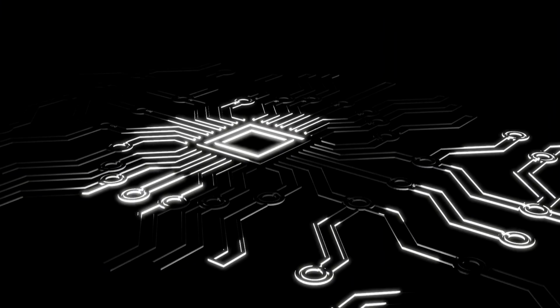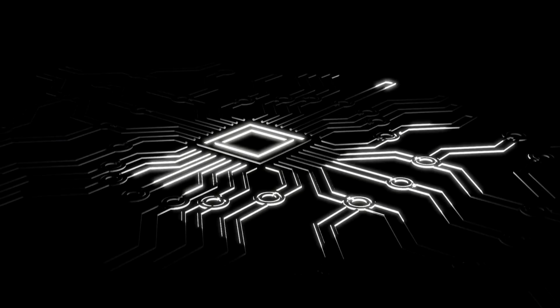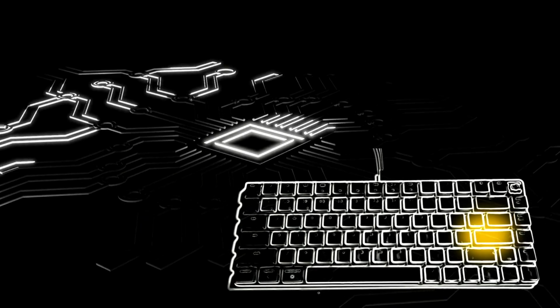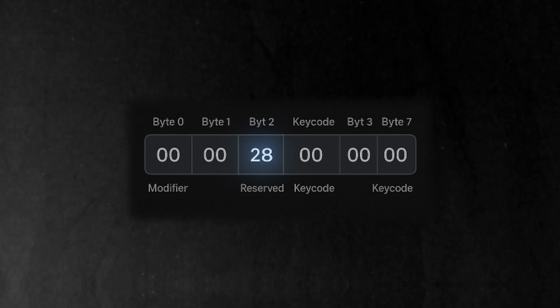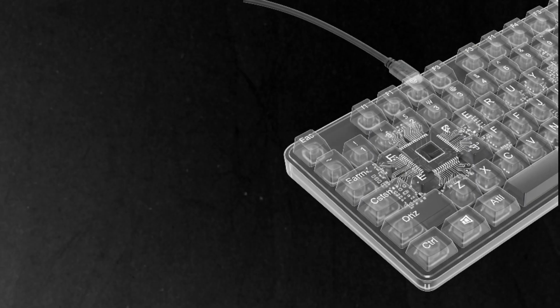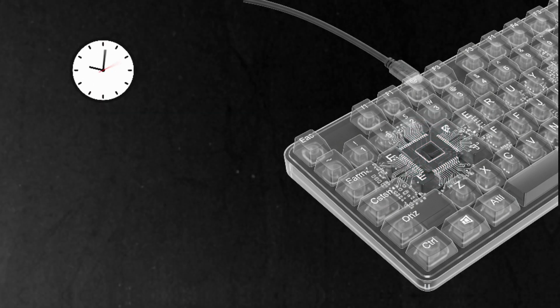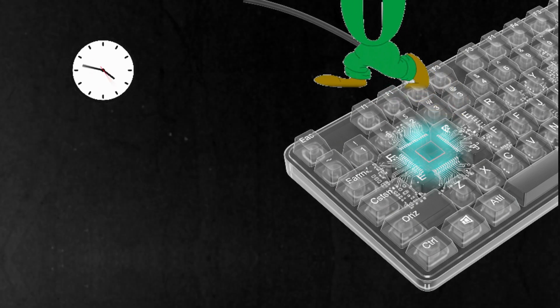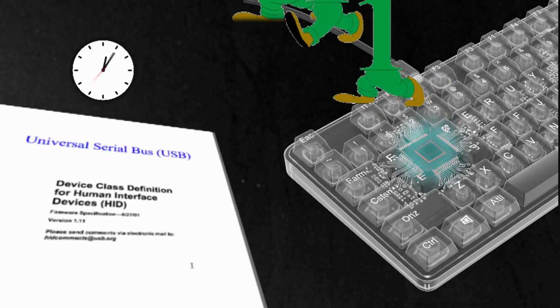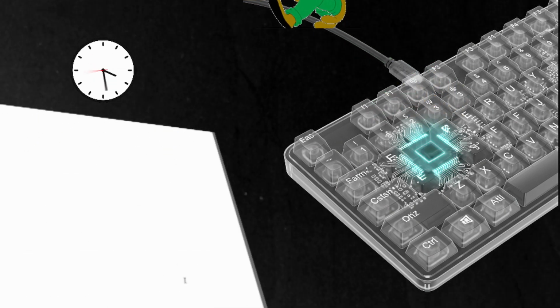Inside the keyboard, a tiny microcontroller is constantly scanning a grid of rows and columns to see which keys are pressed. When it notices the Enter switch has closed, it packages the key's scan code, and any modifier flags into a standard USB human interface device report stored in its memory. Every millisecond, that microcontroller converts the report into a stream of bits, using the USB standard rules for encoding and framing, and drives it onto the data lines.